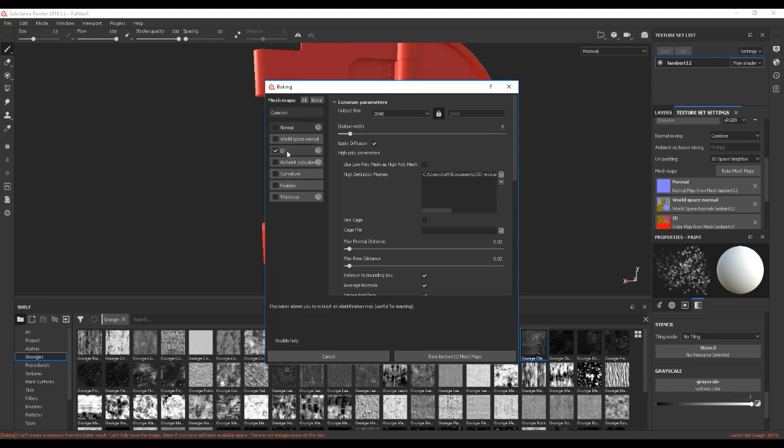And you can see here, I've just got this ID, and I've made two high poly versions. I've made a high poly version with just a basic Lambert material over the entire thing. And then for the high poly detail, I've made another one called ID as well. Now they can be the same thing. You just don't want to have different materials on your low poly version that you bring in, because that's going to bring in more different texture sets here.